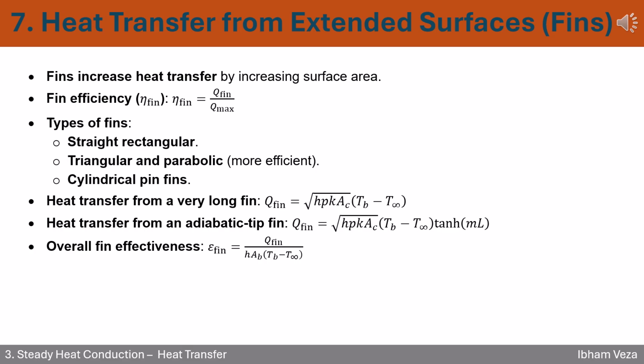Focus on fin efficiency to see how well your fins perform. Choose the right type, rectangular, triangular, or cylindrical, based on your design goals. Simple equations help you quickly estimate heat transfer from fins, especially for long or adiabatic tip fins. Don't forget overall fin effectiveness. It tells you if adding fins is worth it.